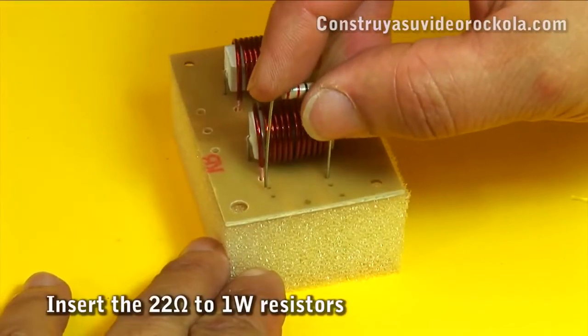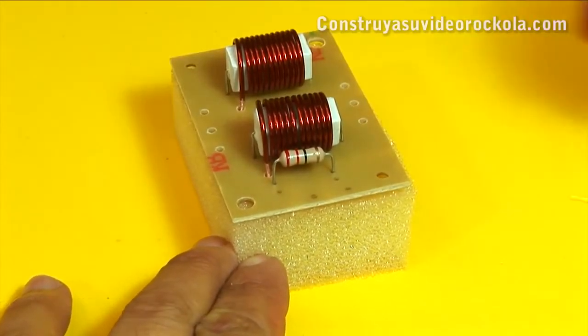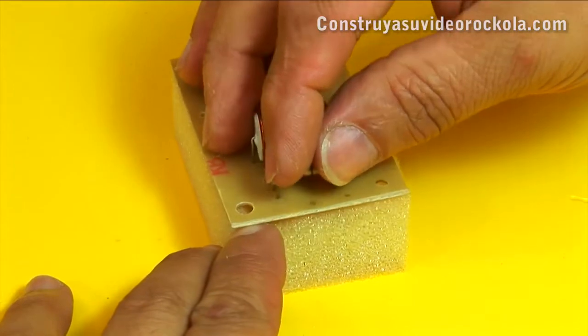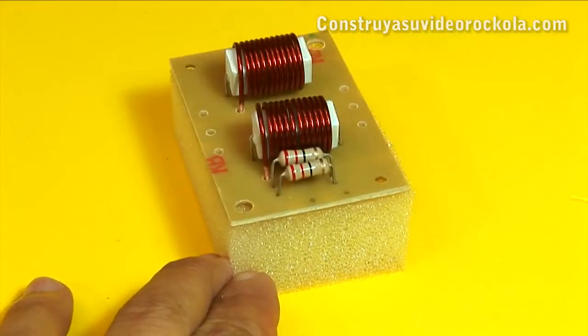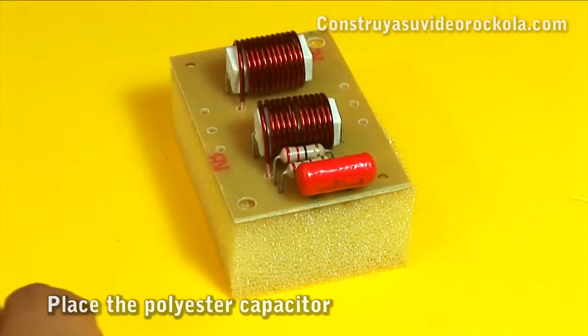Now place the 22 ohm resistors in their respective place. Remember that as the resistors are connected in parallel, they become a single resistor, of 11 ohms at 2 watts. And we put the 0.1 microfarad capacitor in its respective place.